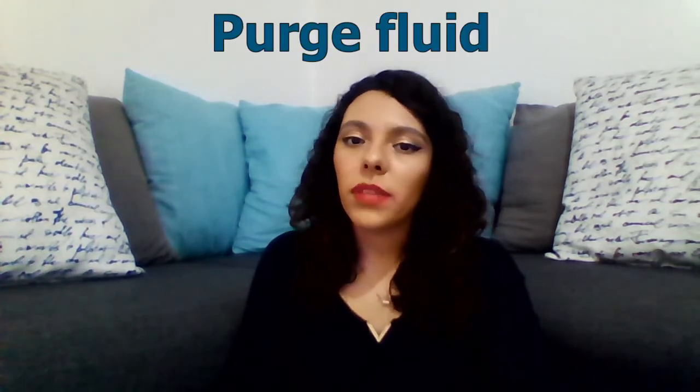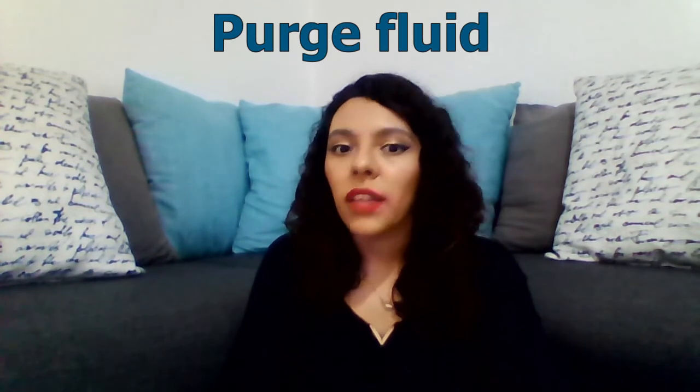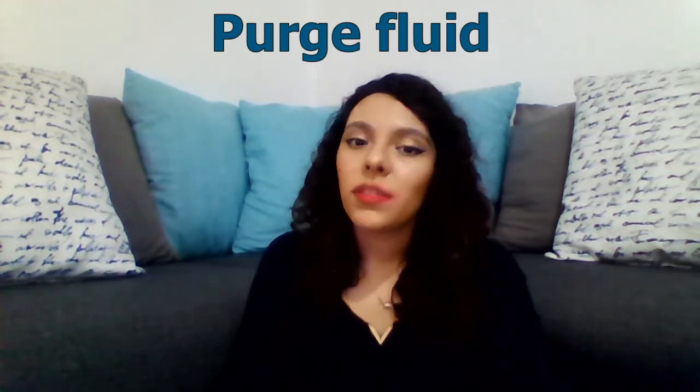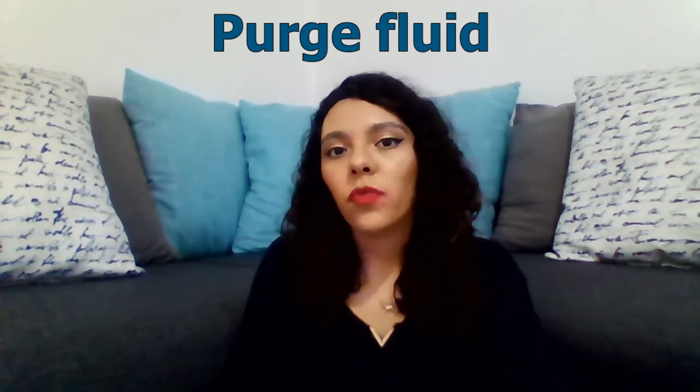The purge fluid must be clean. It must not react with the fluid to be measured, it must circulate at a low and constant flow rate, and there must be a system that prevents entry of the process fluid in the event of purge failure.